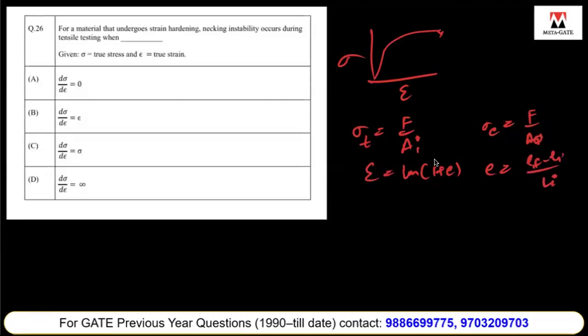Now the necking instability occurs when the material undergoes localized deformation, like during the reduction of the cross-sectional area. This is a tensile sample and the cross-section here decreases a lot due to local necking. At the point of necking, the material undergoes significant stress and strain concentration. This is where the material thins out and becomes narrower due to concentration of stress.